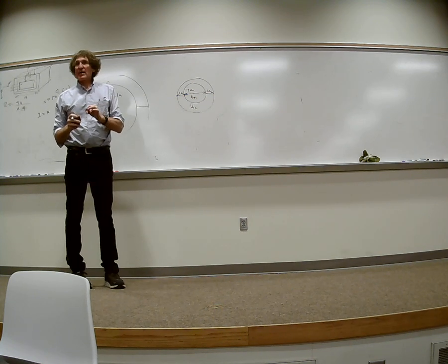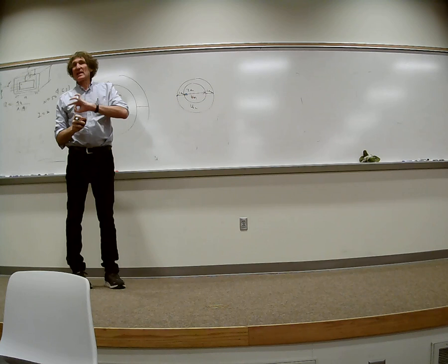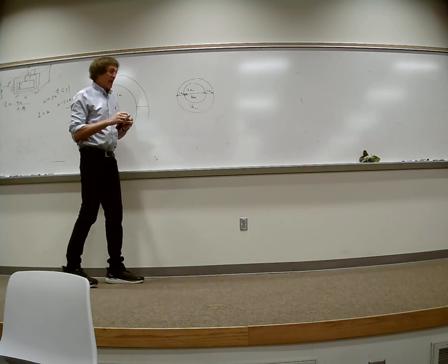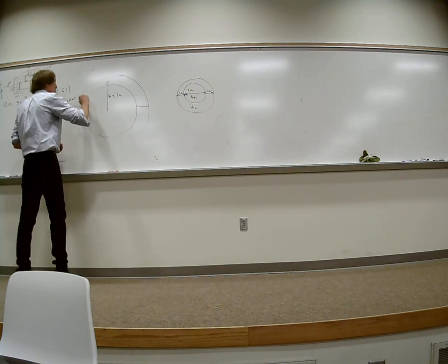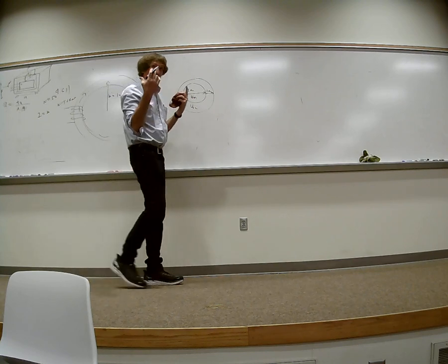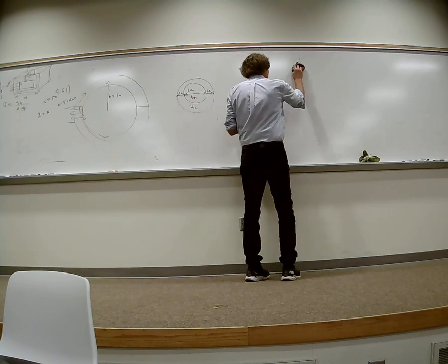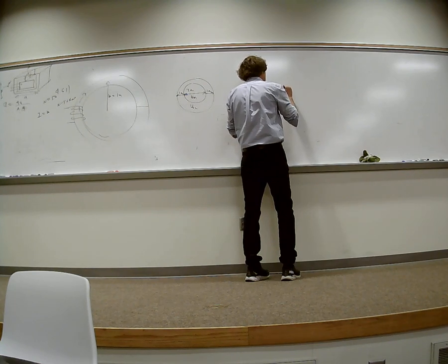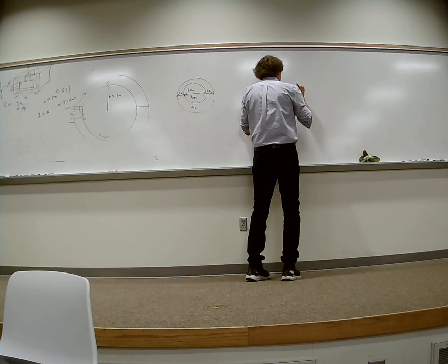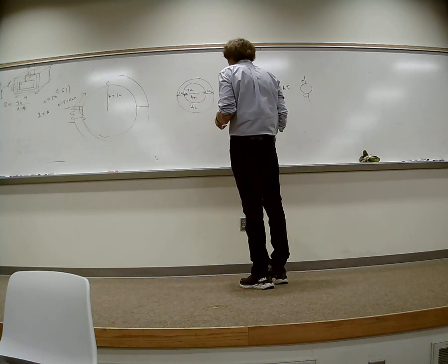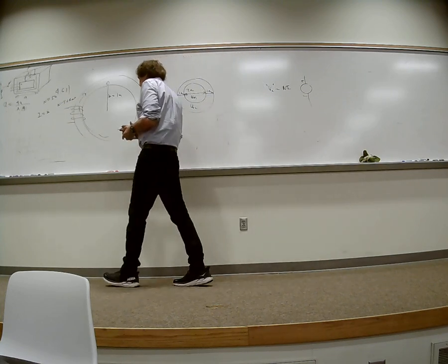Now, if you think about it, what we really have is 2 magnetic reluctances in parallel. You'll just look at that for a second. You all see this? If the magnetic flux is going to be flowing around here, first we'll start with the equivalent magnetic voltage. Think of it as V magnetic. That's equal to N times I. And I'll just put it here. Whatever N is, whatever I is, we just put that there. The next thing we need is the reluctances.